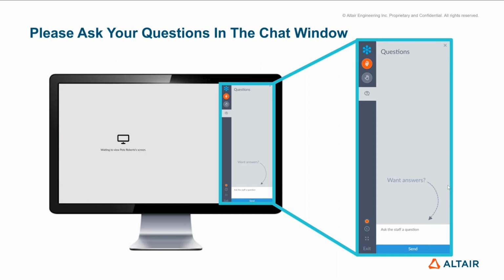There's a question here, a little bit of a longer question, and I think this might be one for yourself, Mike. So I'll read it out. When you see shrinkage within an ingate cavity, as you presented in the example in your die, will you not see shrinkage pulling sometimes into the actual casting cavity? Is the simulation that accurate with location of predicted shrinkage? Yeah, it is. It's pretty good. You can see across the casting ingate interface where you can get shrinkage.